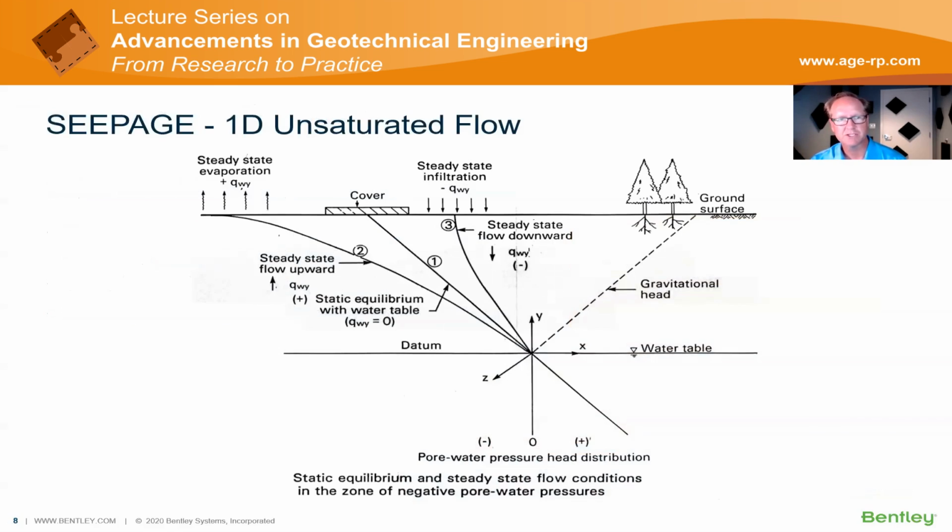We've showed a complex 3D example. Let's back up and just talk one-dimensional seepage flow, just to remind everybody that really we're looking at, if we have a water table and we're only considering vertical flow, then we have a hydrostatic line leading up to a covered material, let's say our covered ground surface. Then we could potentially develop hydrostatic conditions. However, that doesn't usually exist in real life. So we have infiltration that happens, a rainfall, and that tends to pull our pore water pressures over to the right. So you're moving from line 1 to line 3.